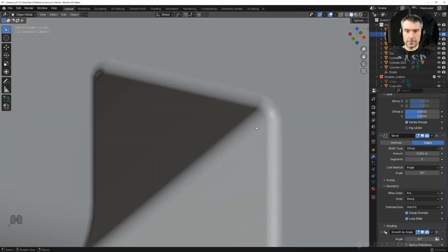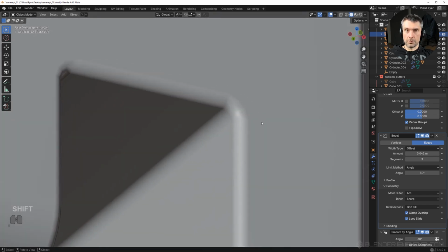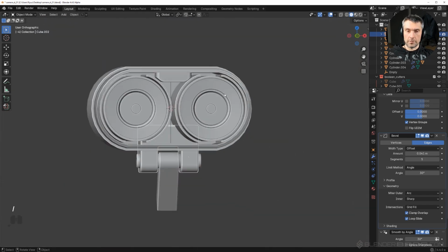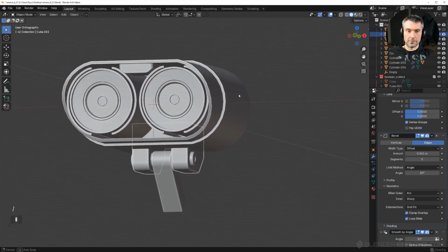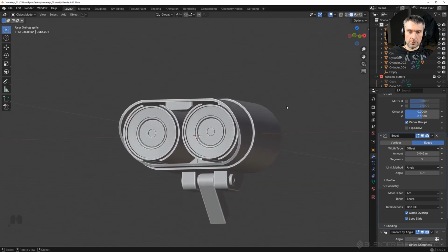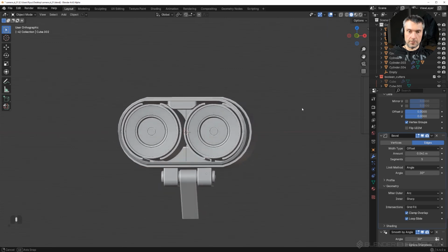And since this is a bigger bevel, this one is a much smoother bevel. The bevel is larger. You might want to increase the number of segments to 5. You see, it's going to be much smoother. So when you have a larger bevel, increase the number of segments, okay? And this would do. I think this would do. This is kind of cool.